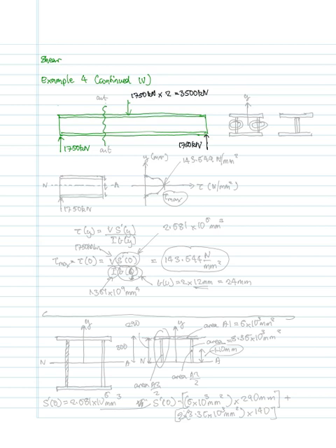Now if we pretend that we're going to make a cut here, so we're going to make a cut there, and then if we draw out the beam again at the position of the cut, there would be a vertical shear force which would give rise to some shear stresses flowing or going down the depth of the web.